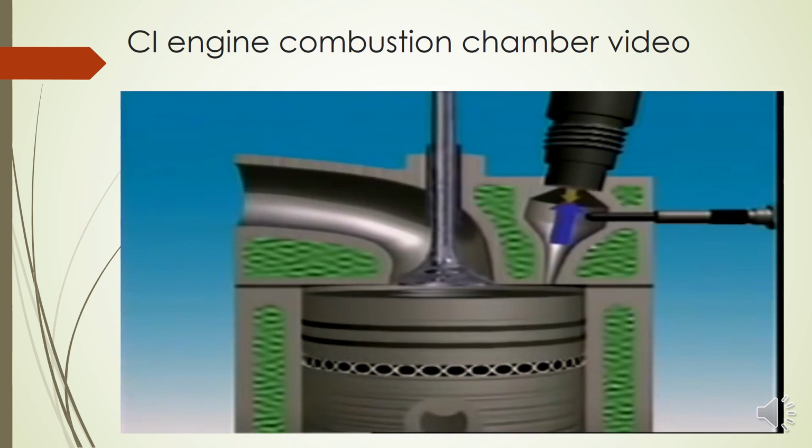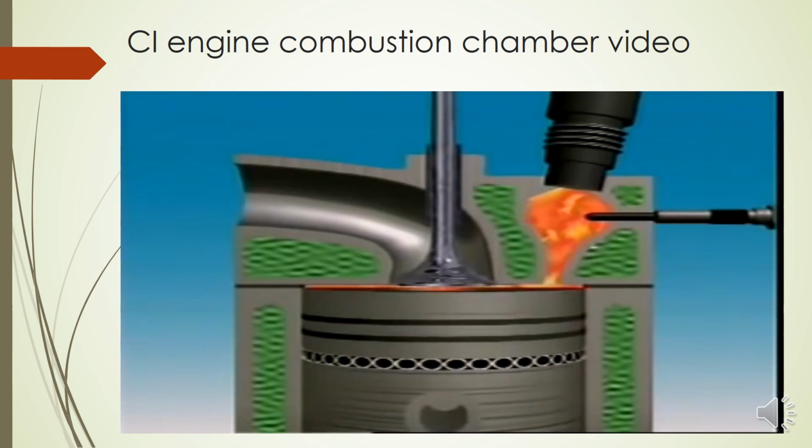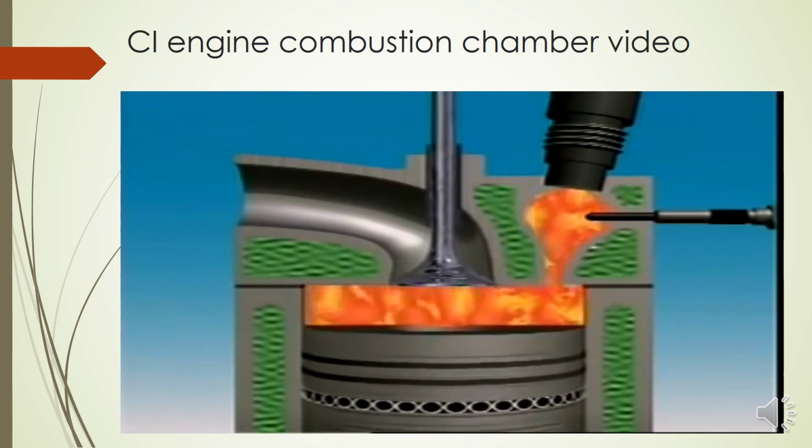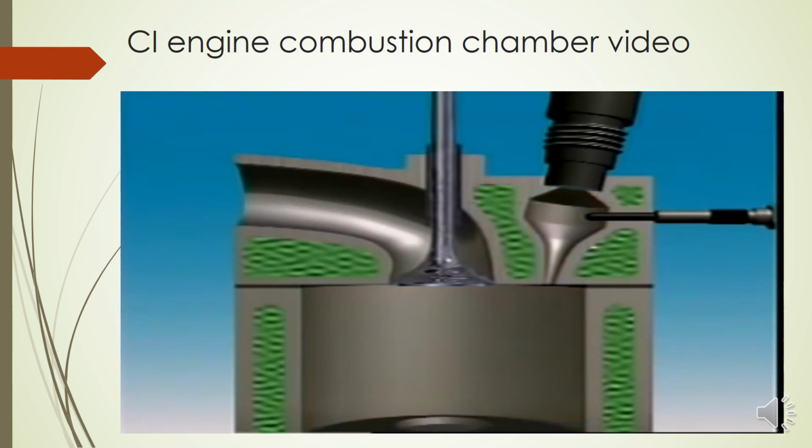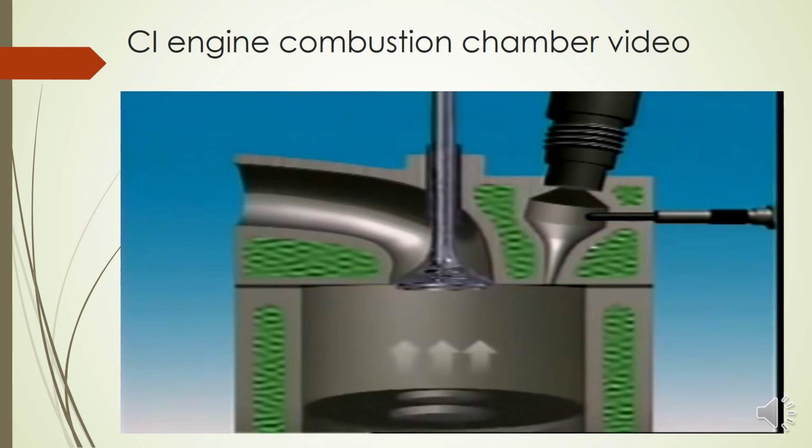Injection occurs near the top of the compression stroke. Only part of the fuel is burned in the pre-combustion chamber because of the limited amount of air there. The high rise in pressure forces burning fuel into the main chamber. This happens very rapidly, which helps make more efficient combustion.